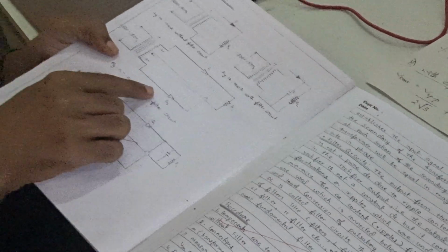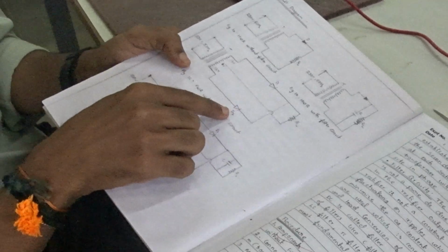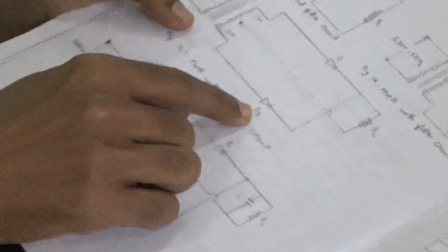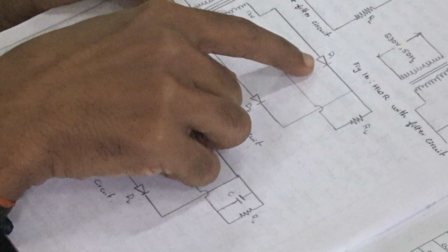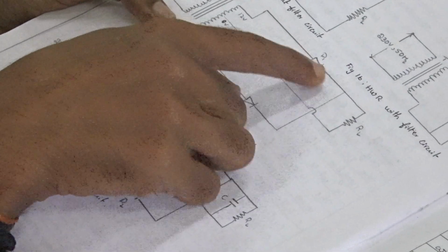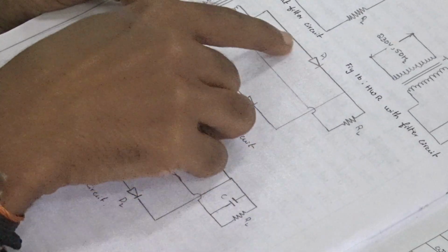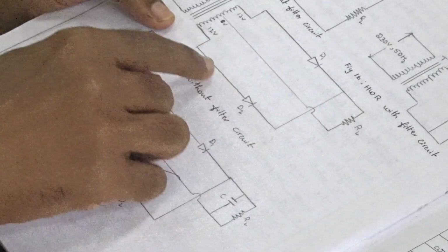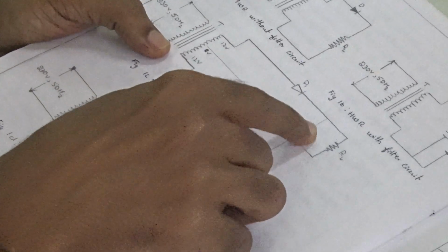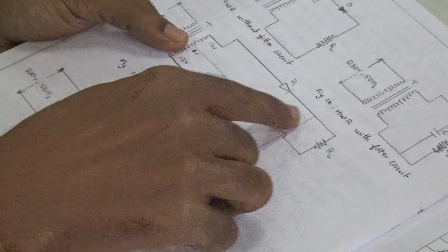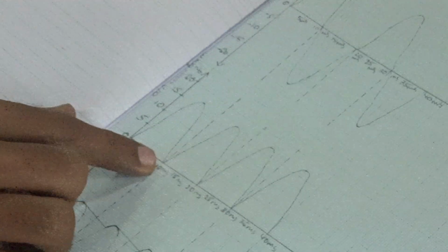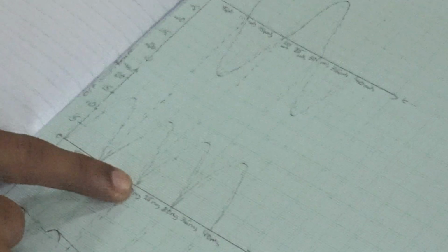During the negative half cycle of the AC, diode D2 will be forward biased, meaning it acts as a closed circuit, and D1 will be reverse biased, which will act as an open circuit, which means there is no connection between the input and output. So a closed circuit is formed like this: the current will flow through the diode D2, through the load resistor and back to the ground point. So during the negative half cycle of the input, we get a positive output.